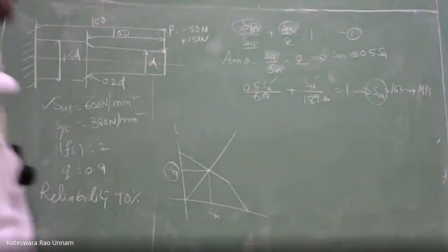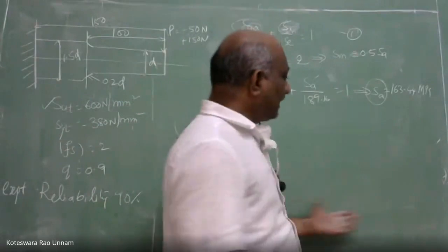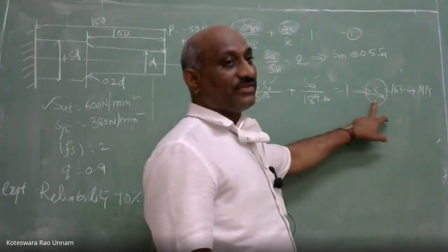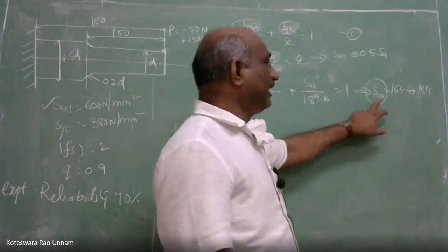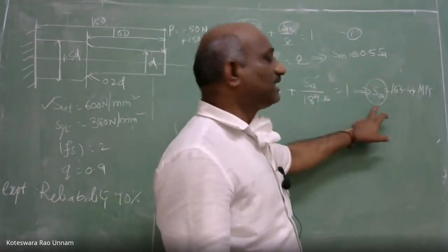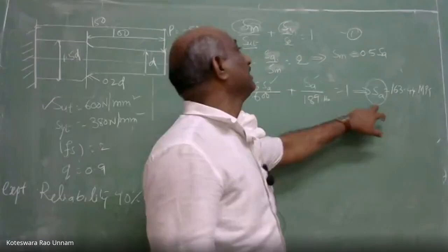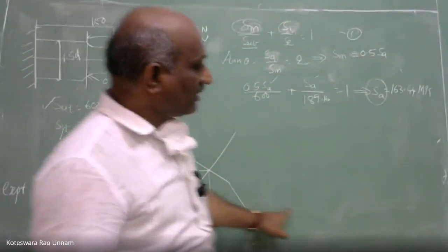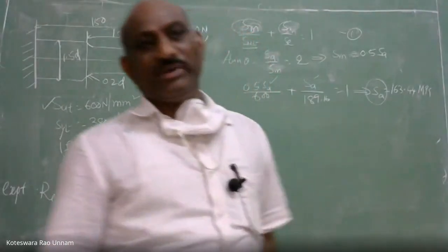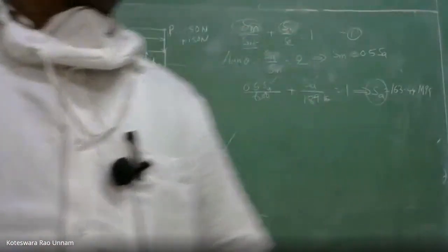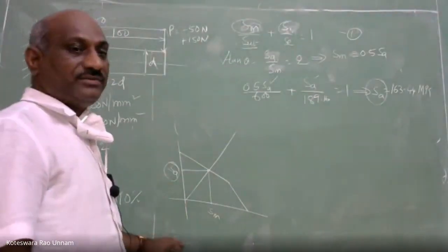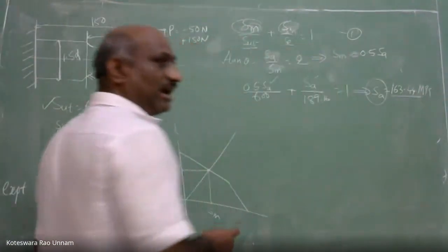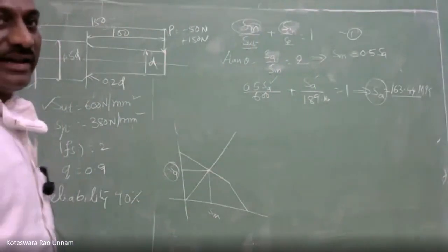So that means actually we calculated the Se value here. That Se is different. Even this Sa is different. So why is it different? Because this is the value of Se we are getting because of the effect of mean stress also. Earlier, whatever Se we calculated, that is because of the working conditions of that component. Now I'll consider this one as the endurance limit.